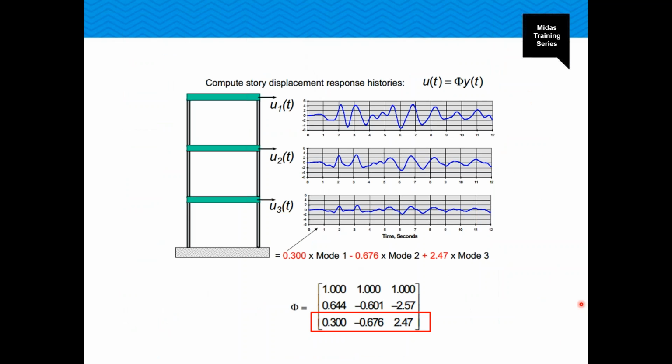Finally, the displacement of the MDOF system. For example, the displacement of the first floor, U3, can be obtained by the linear summation of modal displacements as shown here. Other responses like base shear and element forces can be obtained from the calculated displacements.